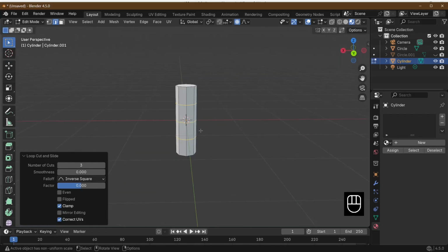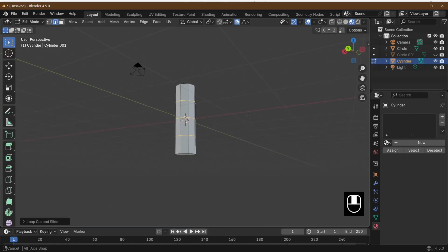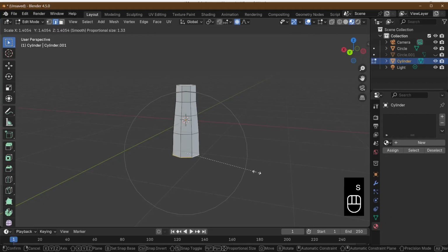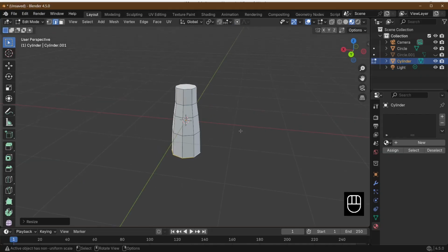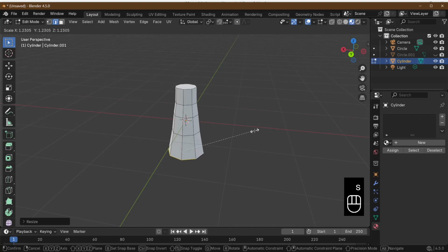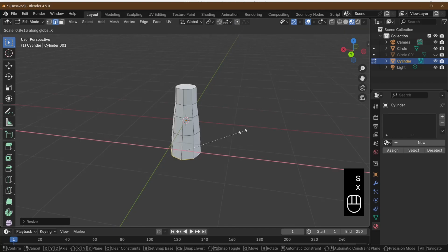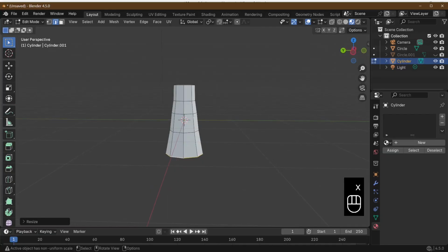So with this selected, what we can do is actually shape this to make our trunk. So if we went on to line select, press the Alt key and selected, we can scale this up. As you can see, we've got an influence ring still applied, so I'm just going to shut that down, scale, scale in the X, so I'm changing the shape of my trunk.